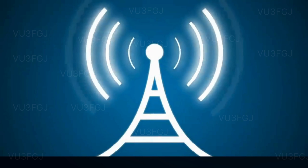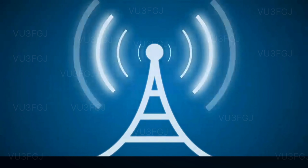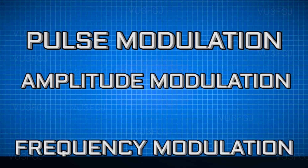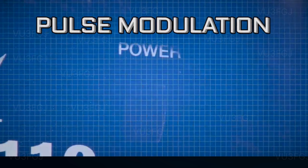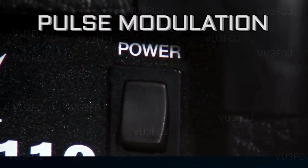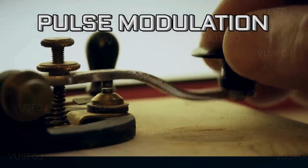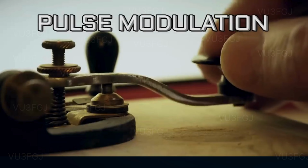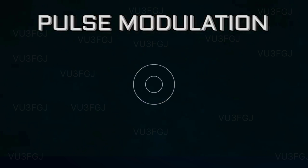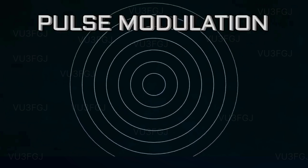You get the point. In order to get sine waves to actually carry information, you need to modulate it. You can do this in 3 ways: pulse modulation, amplitude modulation, and frequency modulation. Pulse modulation means that you turn the sine wave on and off, just like the IT guy suggested. Doing this allows you to easily send Morse code, but that's just about it. Pulse modulation is rarely used except to control clocks across the US. The simplicity of pulse modulation also allows one pulse modulator to cover massive areas, like the entire US.